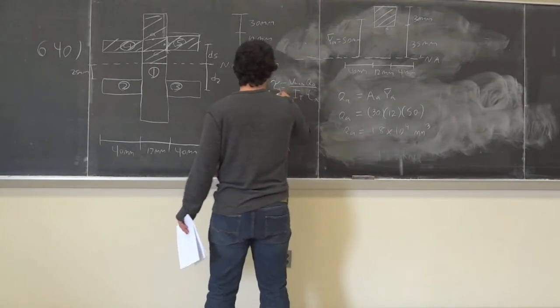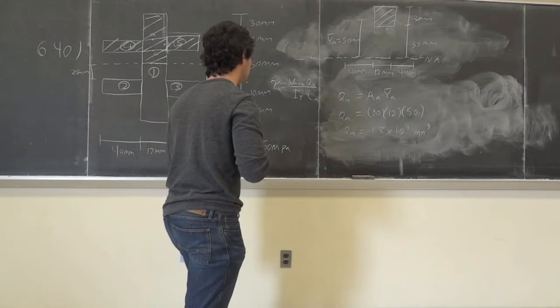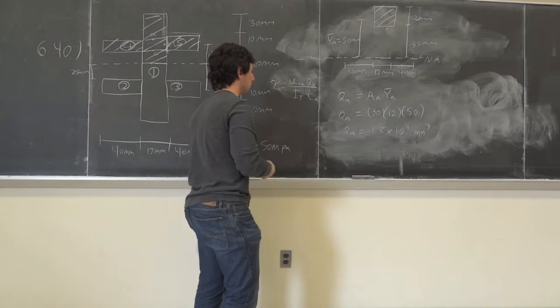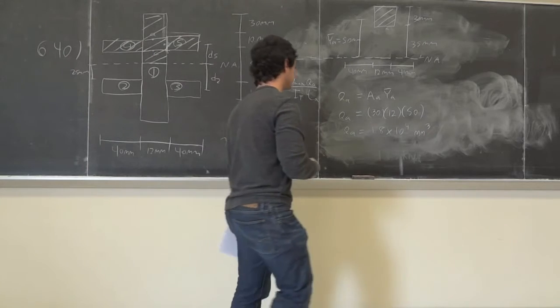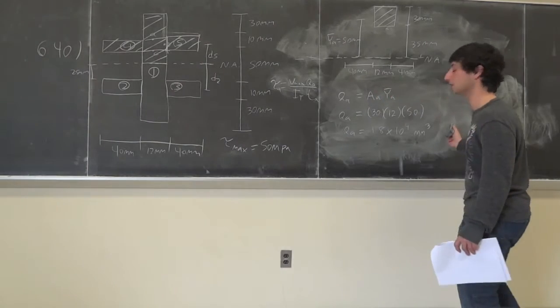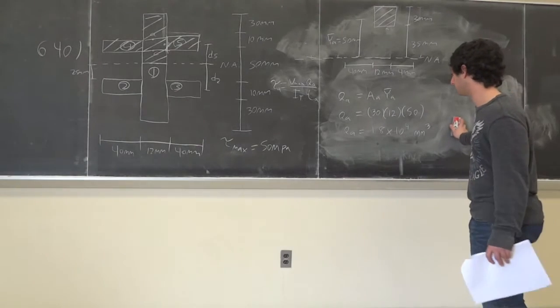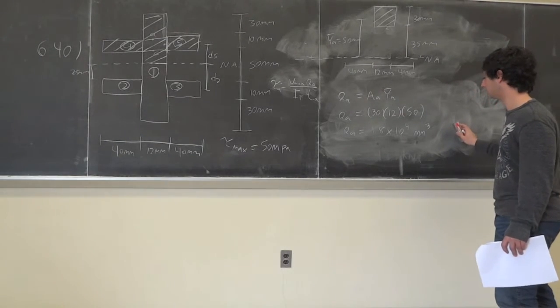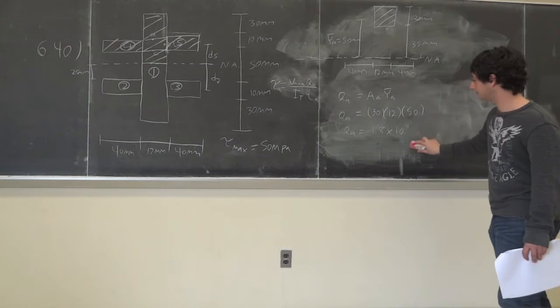So we want to find the transverse shear in section A. So we can just use this formula, VQ over IT. This is the only thing that changed, so we substitute everything else. We can get this transverse shear in that section. It's pretty simple. Okay, so we gotta erase this.